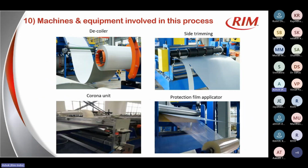So this is in detail. If you see the dry part, the equipment involved in this process starts from the decoiler. These are the upper decoiler and lower decoiler for both the upper and lower sheets. The decoiler can be a single decoiler system or a double decoiler system. Those companies who want continuous production, especially very high volume production, can opt for the double decoiler, which has the sheet joining system.